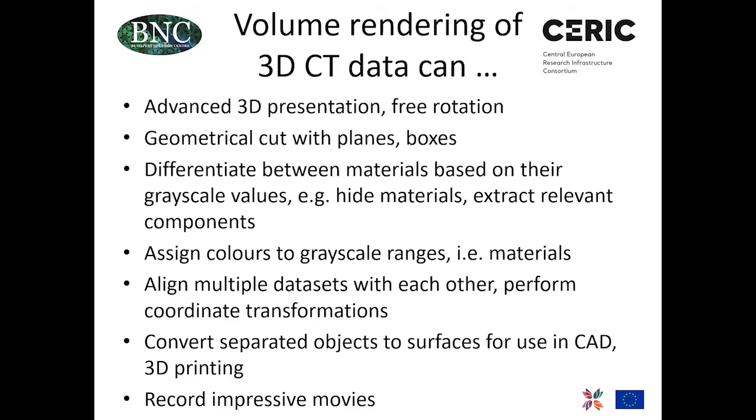We can also create outputs for computer-aided design. So the tomography data can be later used in comparison with the CAD data, or we can use them in 3D printing procedures. So if you compare directly the surfaces from tomograms to the blueprints of the original part, then you can see manufacturing defects easily.